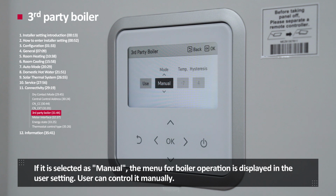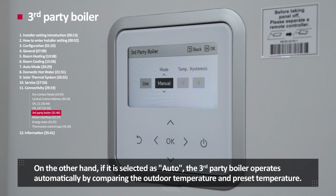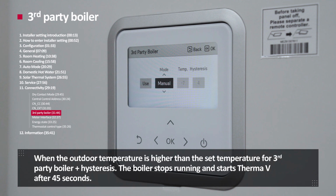User can control it manually. On the other hand, if it is selected as auto, the third-party boiler operates automatically by comparing the outdoor temperature and preset temperature. When the outdoor temperature is higher than the set temperature for third-party boiler plus Hysteresis, the boiler stops running and starts Therma V after 45 seconds.